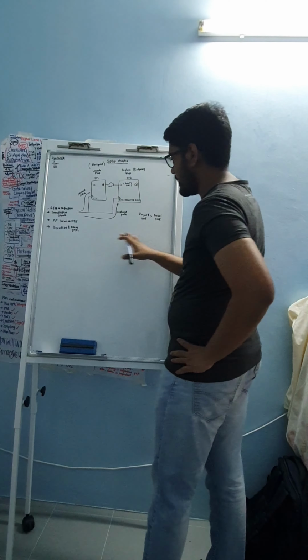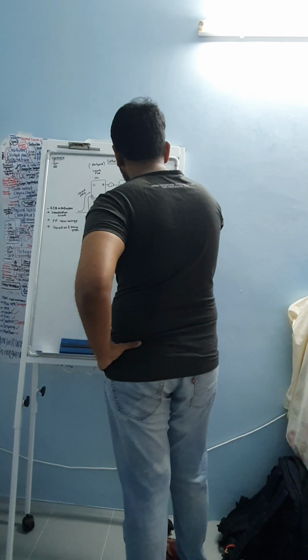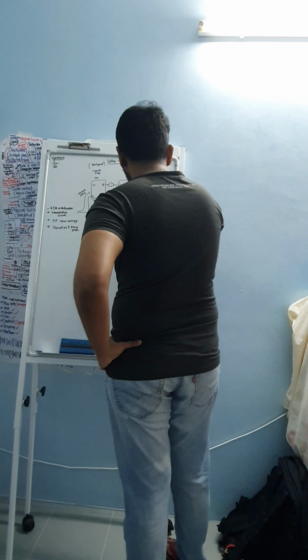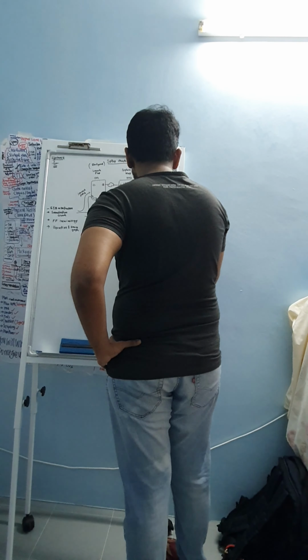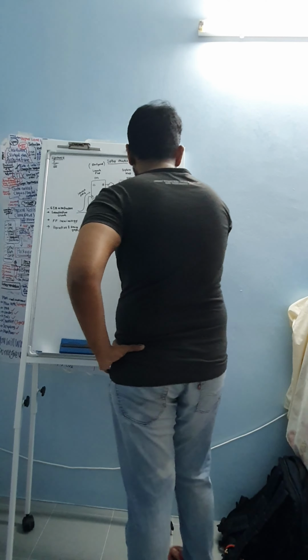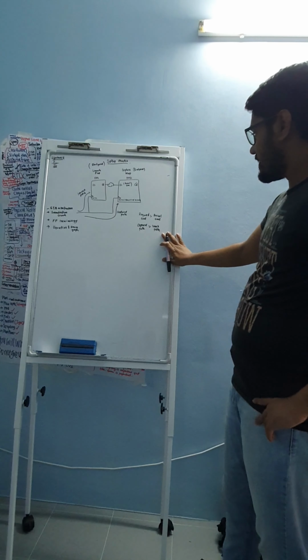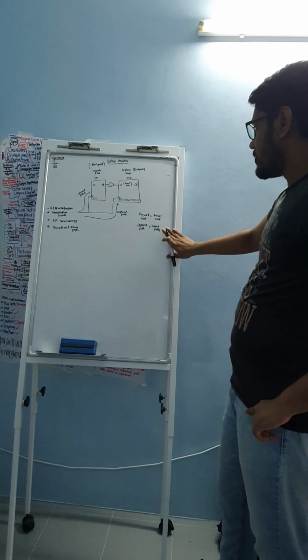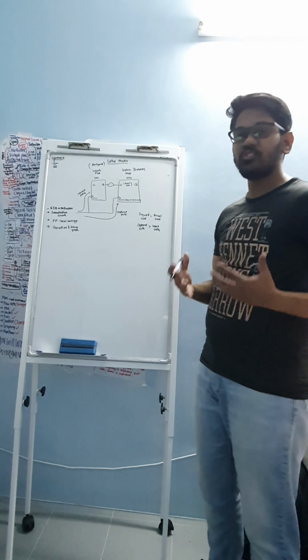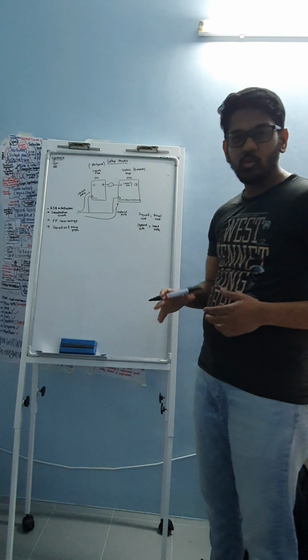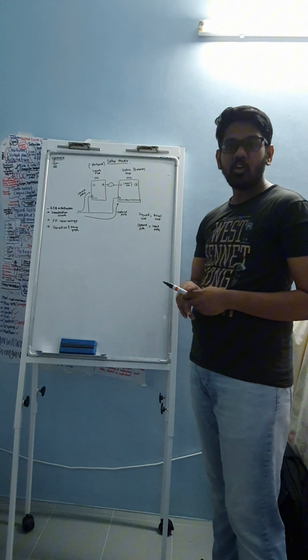In other words, your capture path has to be more than your launch path. In this sense, it means your arrival time, or your launch path coming here, is faster. It has to be fast enough to make sure it is stable before the next clock edge.